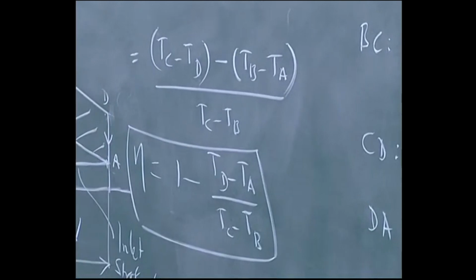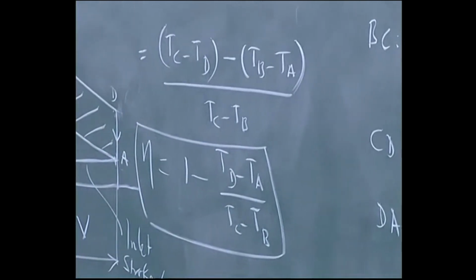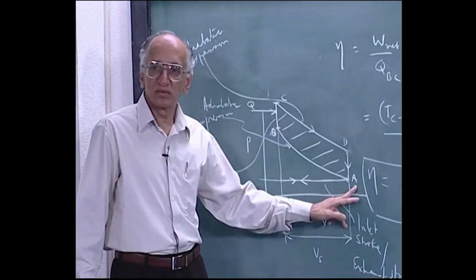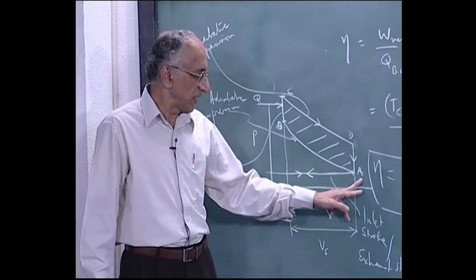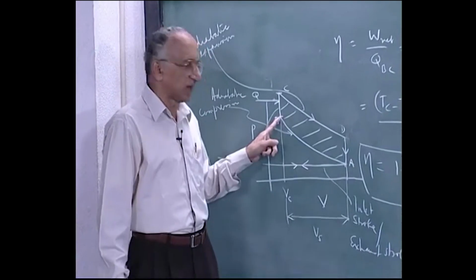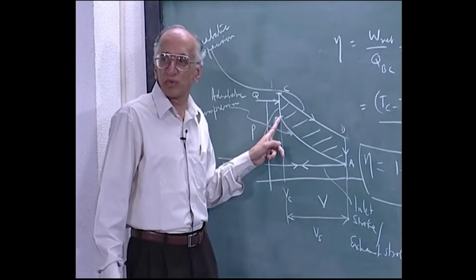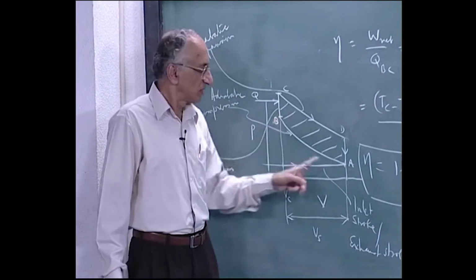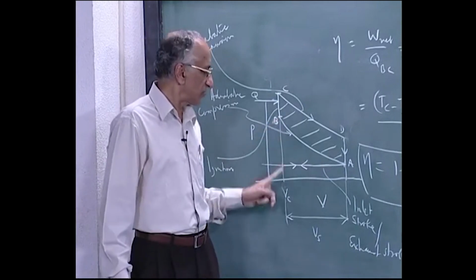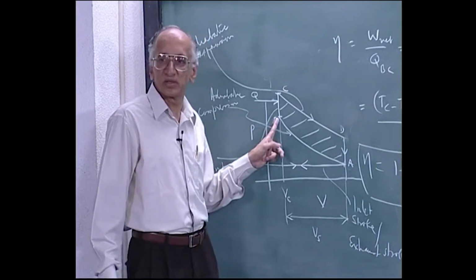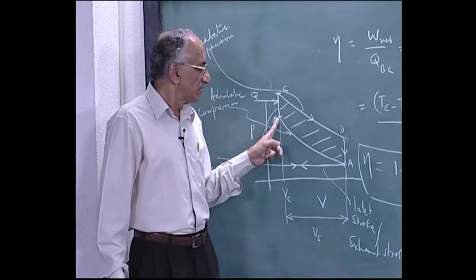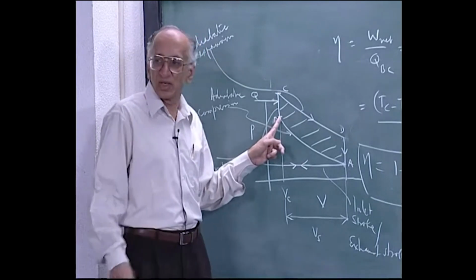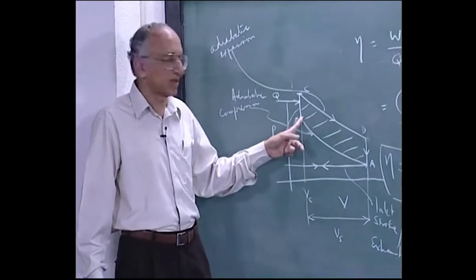All you need to do is calculate the temperatures, and you can calculate these temperatures very easily because Ta and Pa are known. This is adiabatic, so you have your formula PV to the gamma is constant. So from here to here you know this volume, so you can calculate the final pressure here. So once you calculate the pressure, your T is again PV is equal to RT.